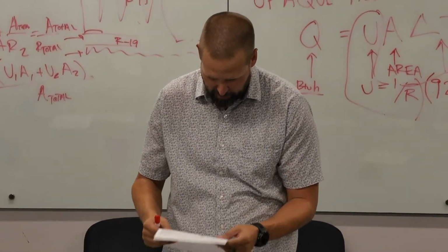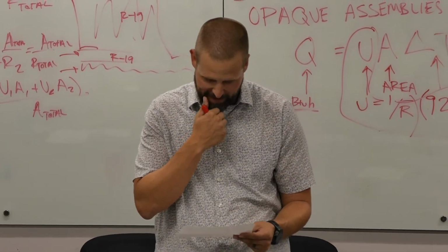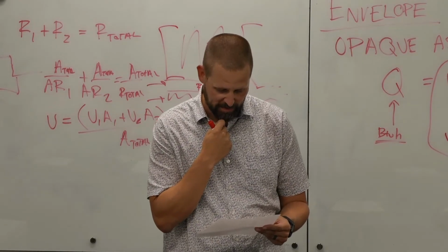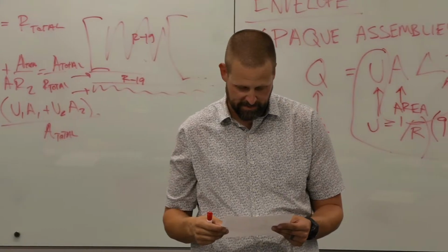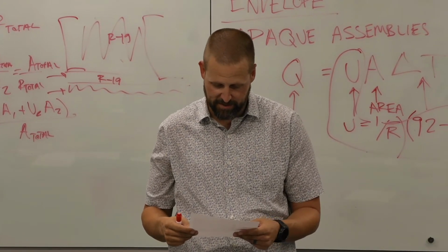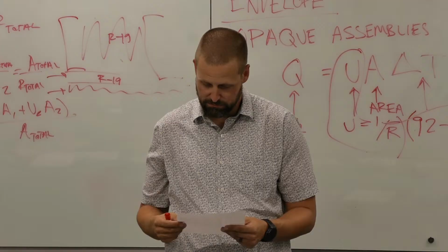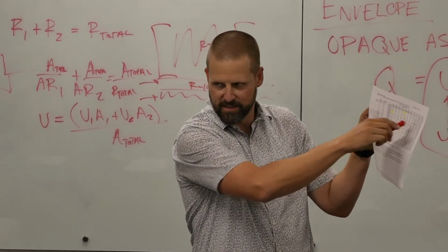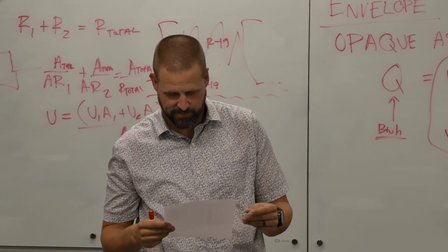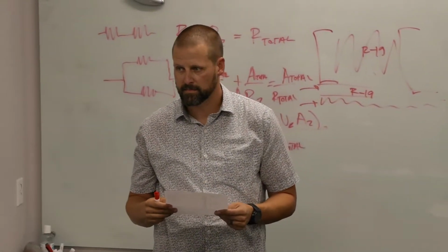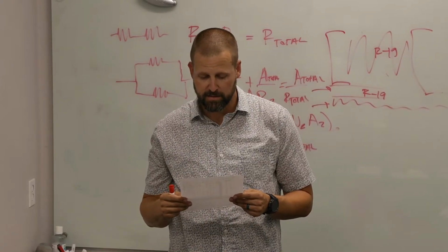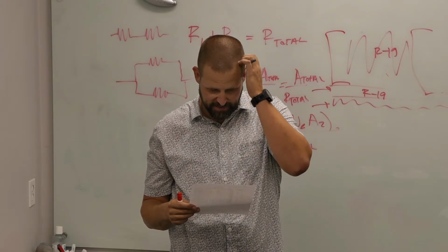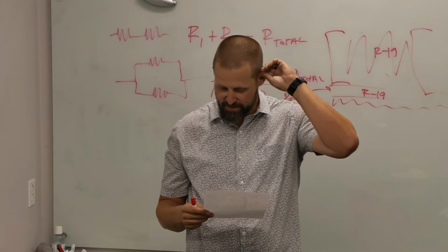So if we look up a 16-inch on center 2x4 metal stud wall with no continuous insulation and R13 cavity insulation, what's the U factor? And the U factors are all the numbers in here. Repeat: R13 cavity insulation, 2x4 framing, 16 inches on center, no continuous insulation.